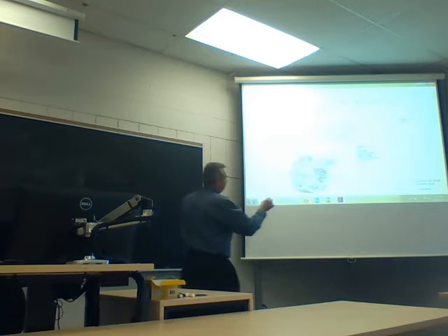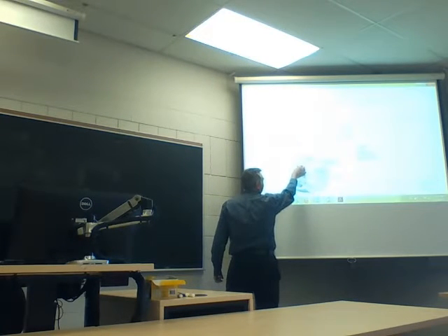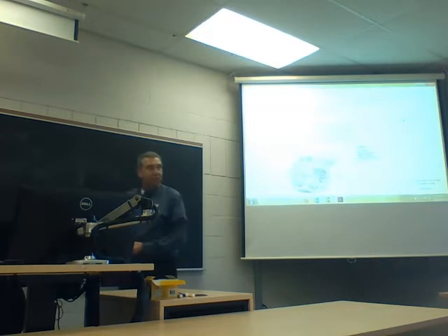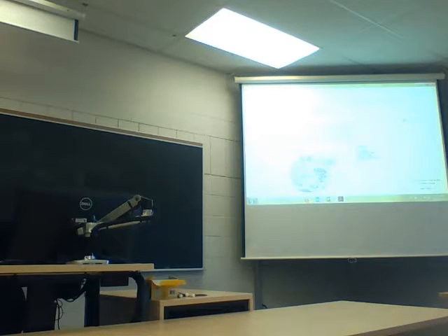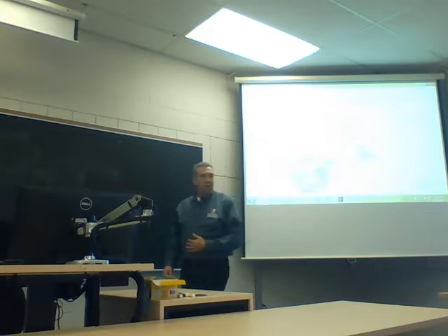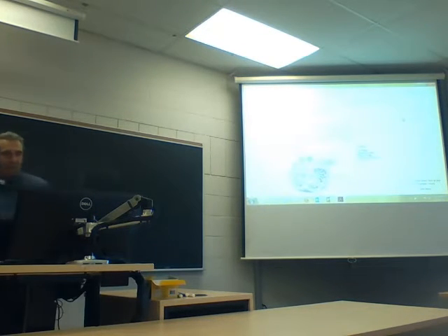It's tighter here and wider here, so we take velocity and convert it into pressure in this particular model. You see how they go from narrow to wide, the same as the volute goes from small to large. Same concept.